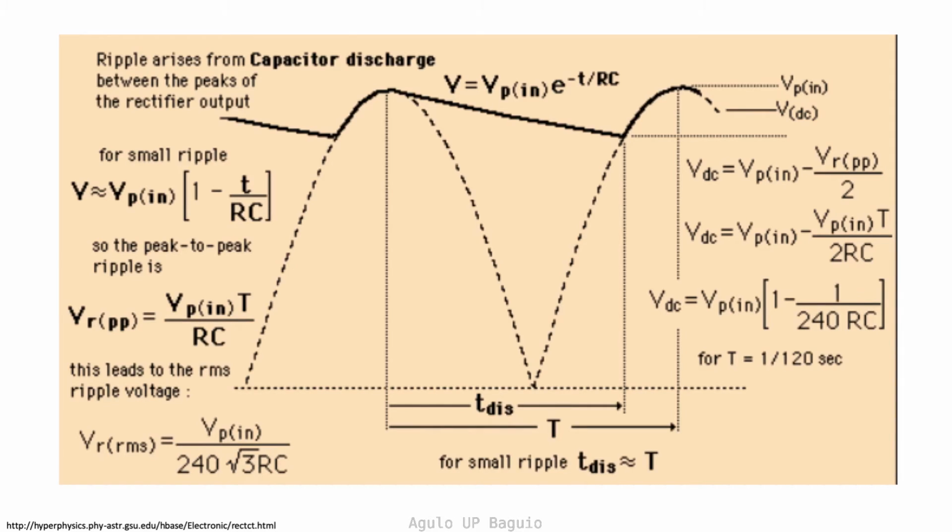The factor of 1/2 is inherent in the RMS equation. The square root of 2 is obtained by taking the root mean square of the sinusoidal function. The mean is understood to be an integration over an infinite number of cycles. However, since the ripple function is not really a sinusoidal function, the RMS result is actually square root of 3. I have included a link in this topic's suggested links describing and showing this calculation. Feel free to take a look at it.